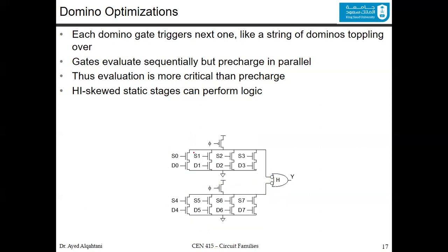The thing that you should be aware of is the value that shows here. If you select D0, so this will be on. D0, whatever the value, 0 or 1, let's say it's 1. So this is on, it will go here, it will be inverted. And from this path here, you will get nothing from this side. So it will be inverted, and then the result here would be D0 bar. So it's like an inversion, or the inverted multiplex.